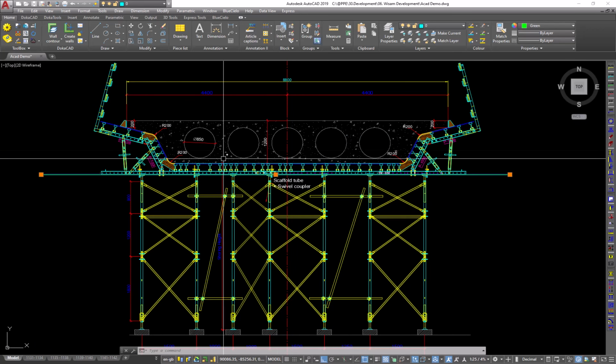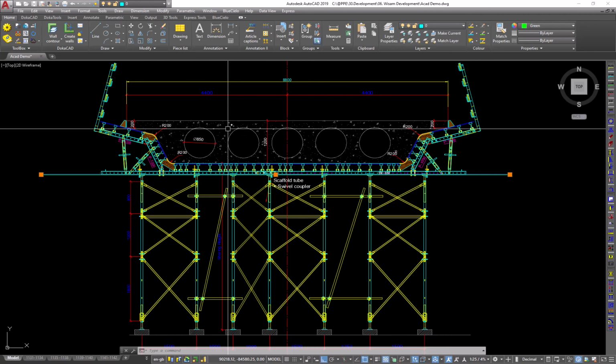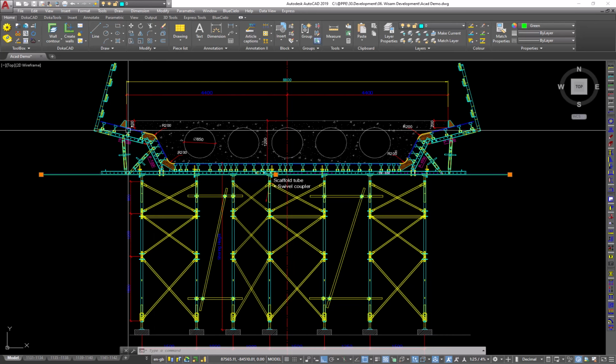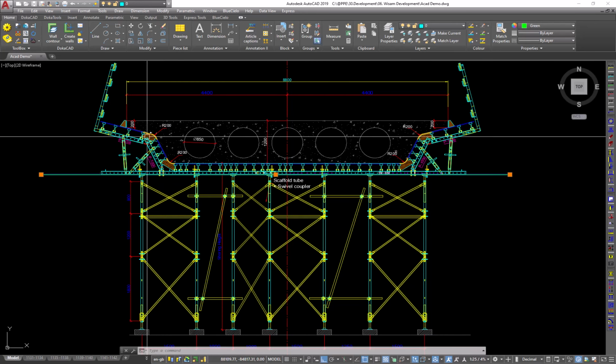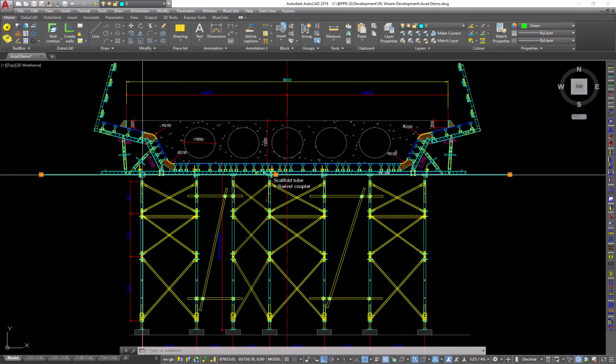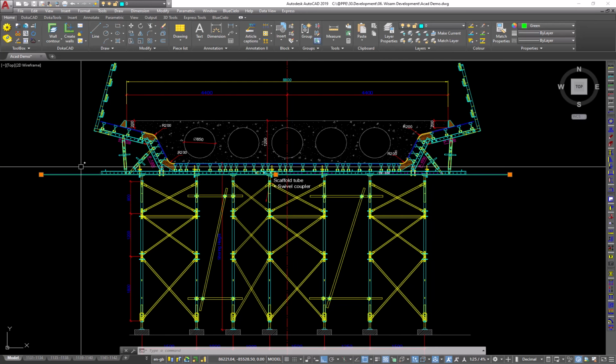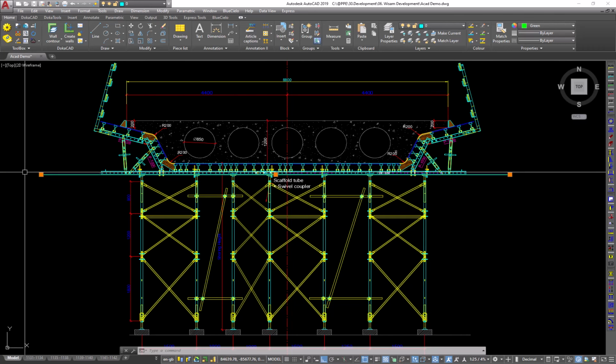The script can automatically take coordinates from the surface above them, but the problem is in these areas where the bridge goes up and the tower needs to finish here instead of here. So that's why we need to create something temporary up to this level where the towers would end. And for that we will use our custom-made Dynamo pre-processing script.